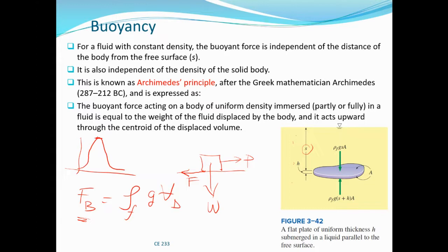It reaches a maximum. And from this point, any increase in P will now set the block in motion, because it means the applied force has overcome the frictional force. The frictional force is like a force trying to prevent the relative movement of the block. Okay, so once you apply P greater than the frictional force, then that is the only condition when the block will be in motion. Okay, so this is the limiting frictional force, the maximum frictional force.